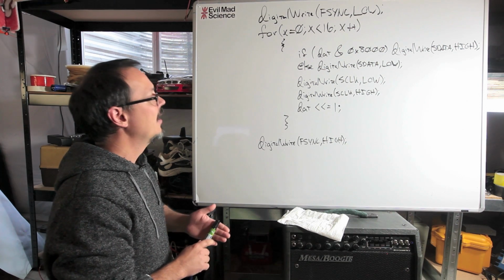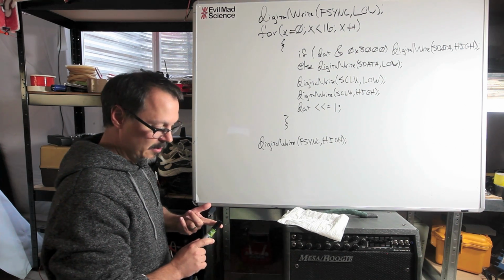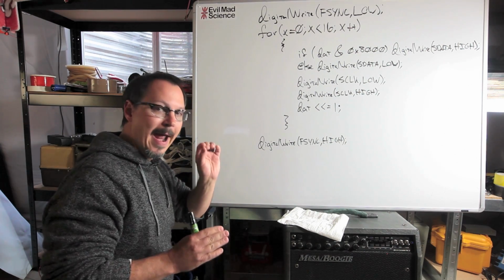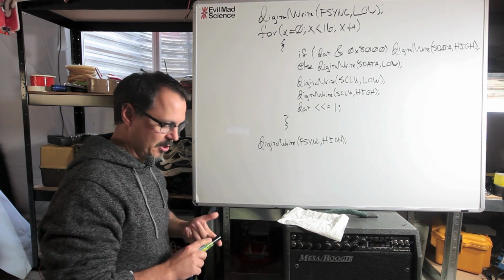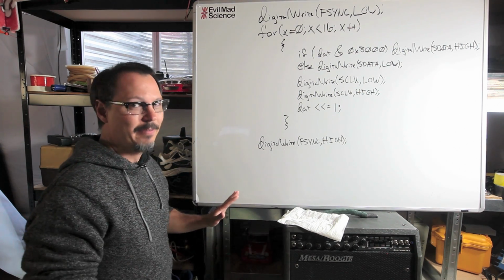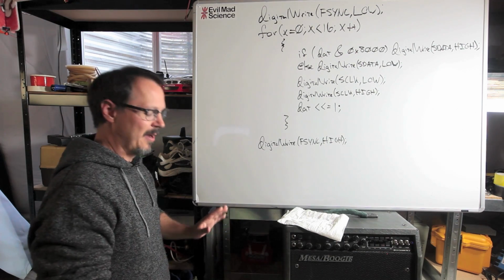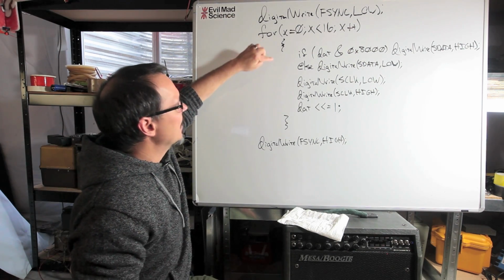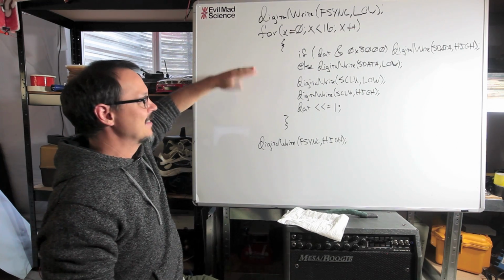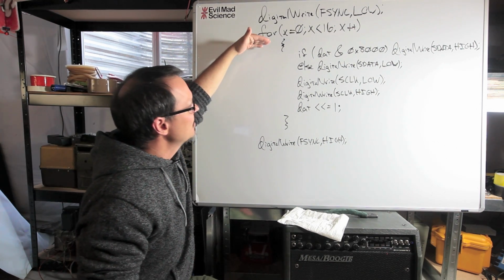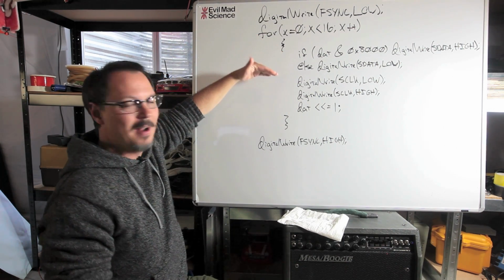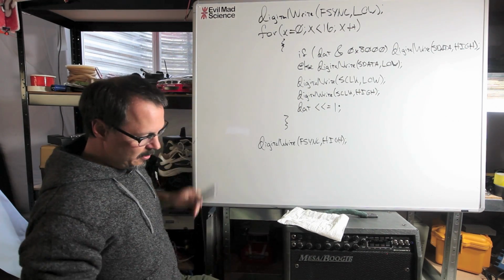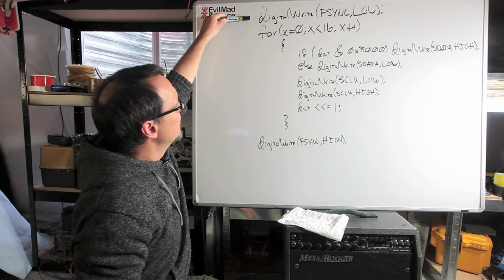Now the timing diagram of the part, the AD9837, all of its minimum timings are in nanoseconds, single digit, some double digits, nothing that even approaches 62.5 nanoseconds, right? So the point of that is I can bitbang this thing and I don't have to worry about delays, because as long as I'm doing one thing per instruction, I'm never going to come close to that minimum limit.